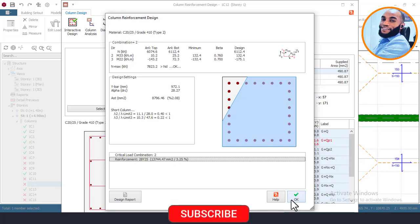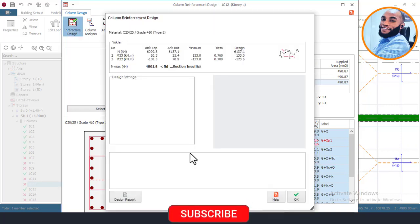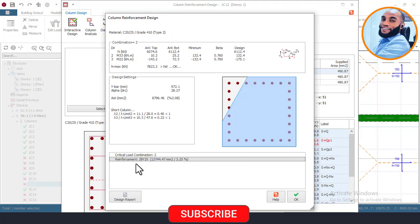So right now you can see that the width of that column before was 600. So that was not able to carry the weight coming to that column. So we have now increased it to 650. And we have checked that again and it's okay. As you can see, it is showing the bar quantity and the bar size. So with this now, this column looks okay.